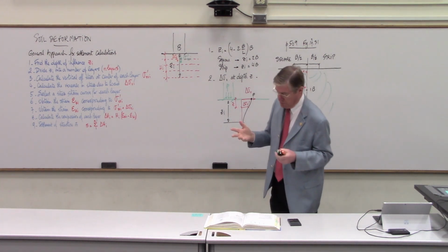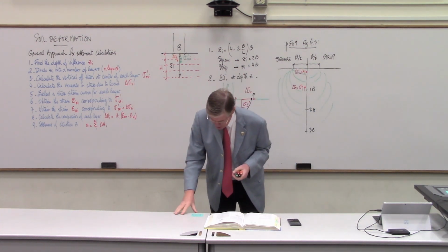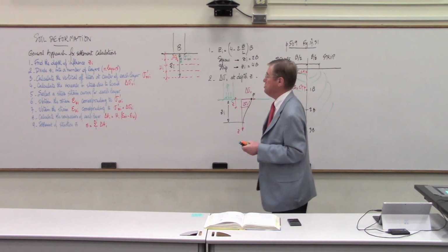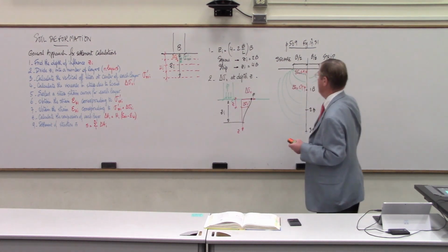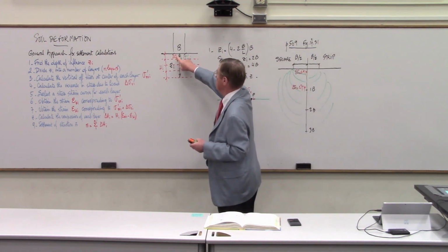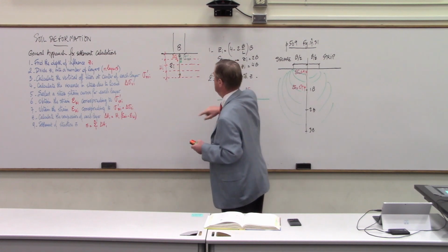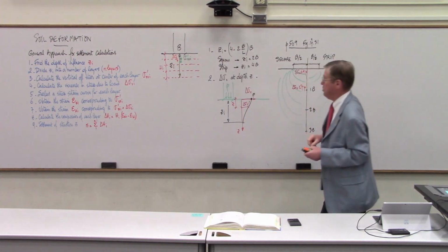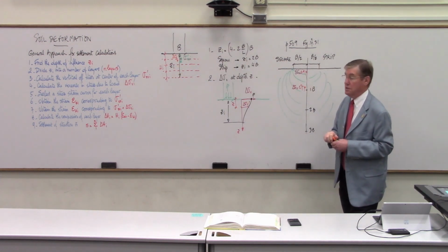So that's how we obtain the increase in stress as a function of depth. Because remember, we need that increase in stress at the center of each one of those layers, and using these bulbs of pressure, that's how we get these increases in stress.